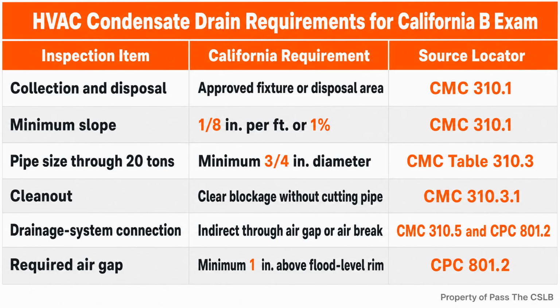Imagine a crew installs an air handler in an attic above a finished bedroom. The primary drain looks clean on rough inspection. Months later, that line becomes blocked. If there is no effective secondary protection, the first visible sign may be damage below the unit. If there is a properly coordinated overflow switch or secondary pan with an observable drain, the failure creates a warning or stops the equipment before the same condition silently reaches finished work. That difference is the heart of condensate coordination.